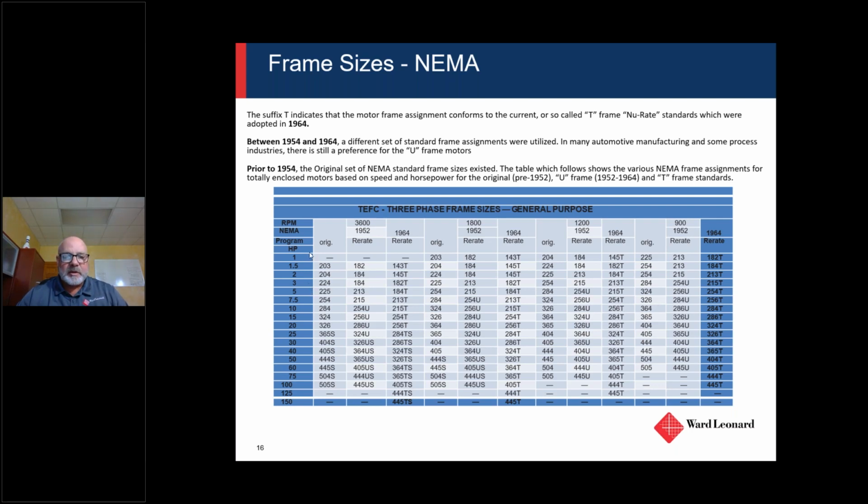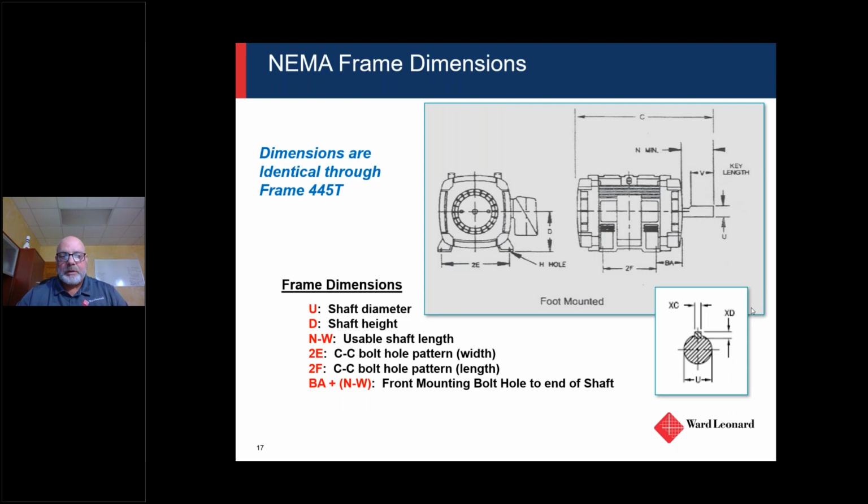Right? This all standardizes pretty much through this 445 TS frame. And really that is through any OEM. If they're manufacturing NEMA type motors, then the frame size is going to be consistent. Okay? And when I mean consistency, this is what we're looking at, right? So this is your frame dimensions.